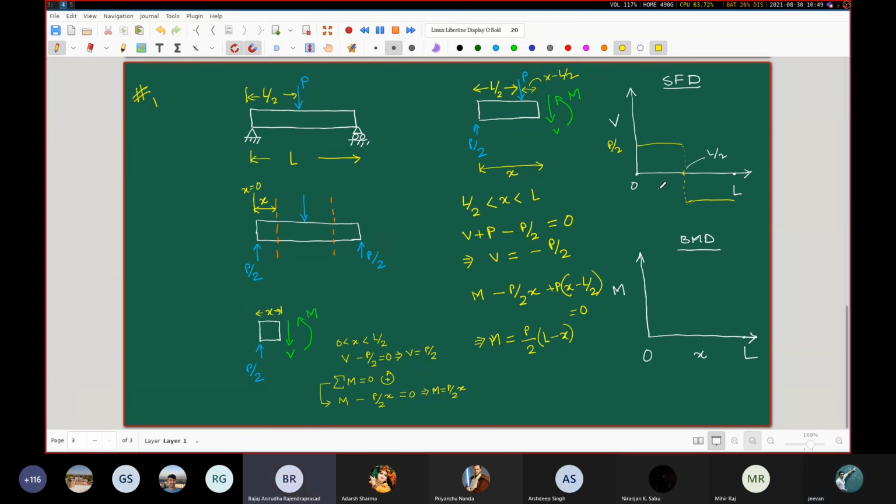Generally we take the upper side as positive and the lower side as negative, no? Yes, but you are taking the downward pointing V as the positive here. That's why it's coming like this. If someone takes the reverse, the diagram will look like a reflection. Worldwide, this is the accepted convention. So even without mentioning anything else, if you just draw the shear force diagram like this, people will understand what you are doing. This is the accepted code among engineers.